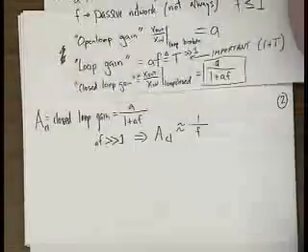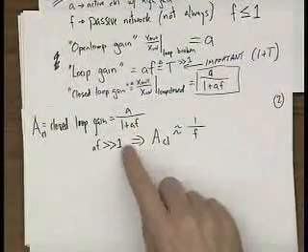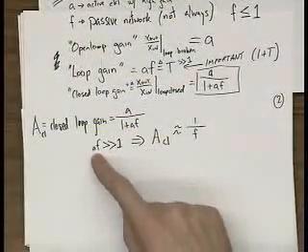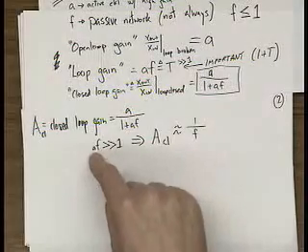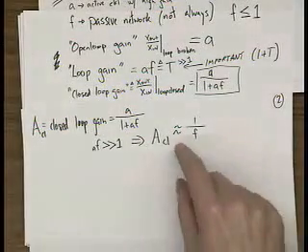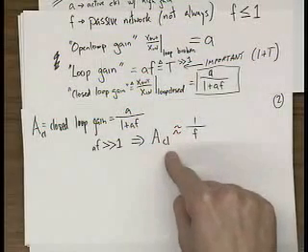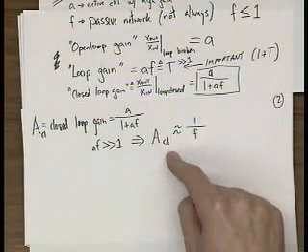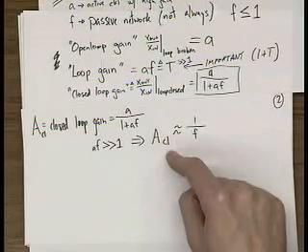So you can see that to first order, provided that AF is large, changes in A, which will invariably happen because of process variation and such, don't really change the overall gain of your circuit. So it's called gain desensitization or gain stabilization.